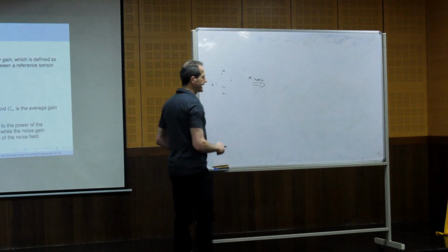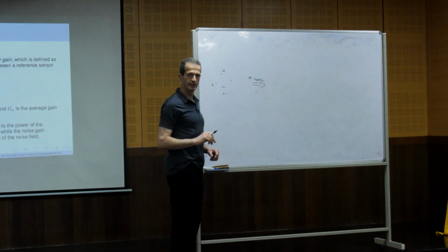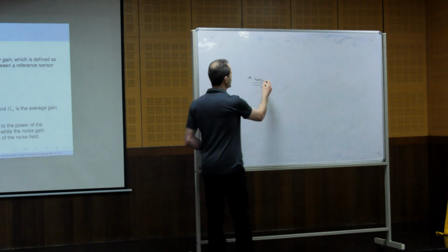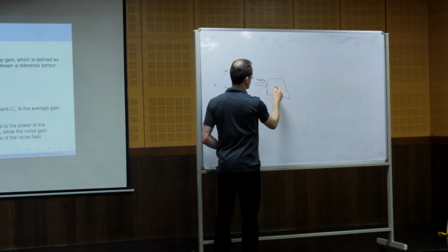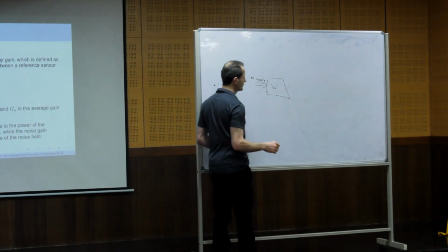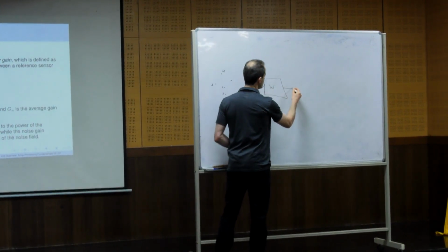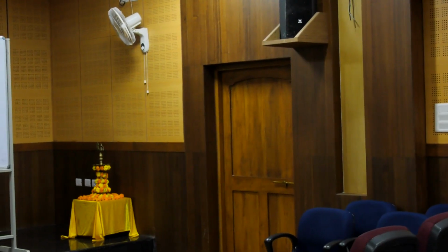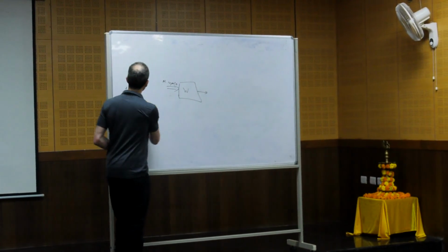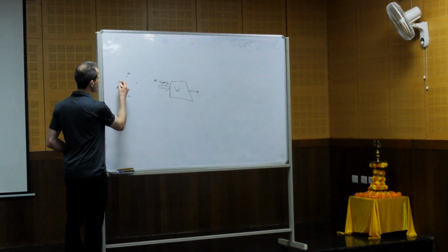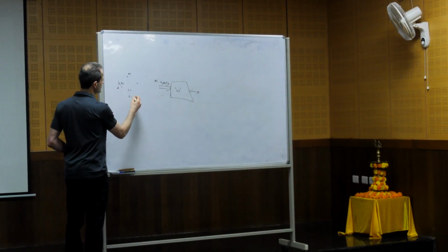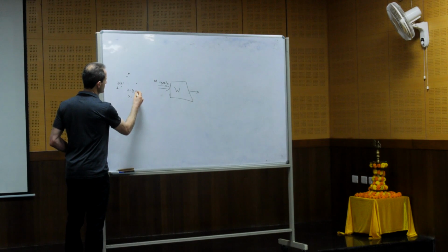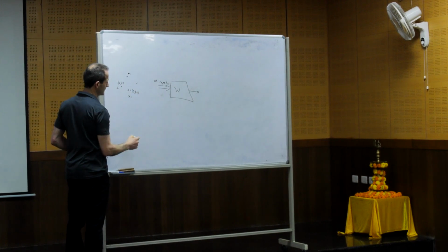We multiply each sensor signal with some weight. Let's call it W. And then we have the beamformer output. We will talk about it more, but usually we take the signal that is received in each one of the sensors, y1(t), y2(t), and so on, all of them.